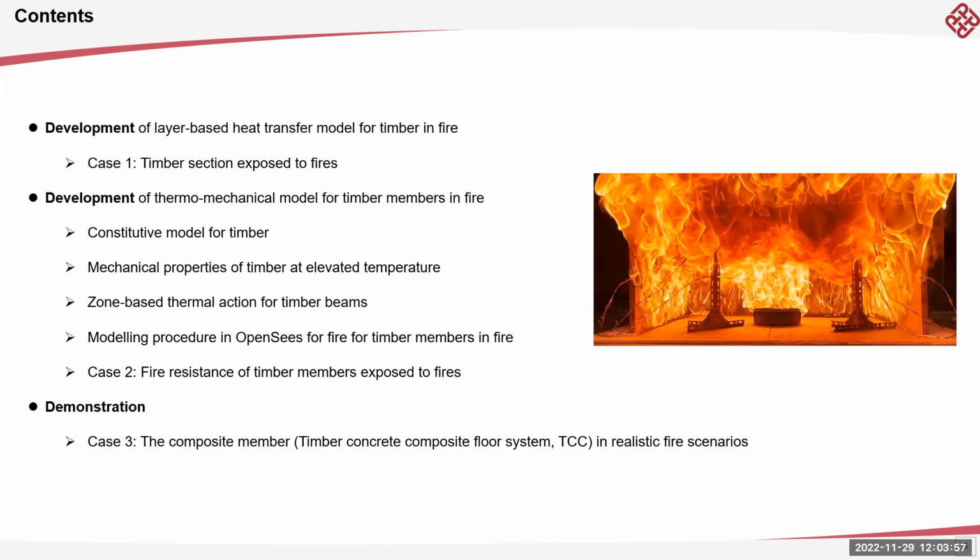And the second is development of a thermomechanical model for timber members in fire, including the constitutive model for timber, mechanical property of timber at elevated temperature, and zone-based thermal action for timber beams, modeling procedure in OpenSees for Fire for timber members in fire, and a case two about fire resistance of timber members exposed to fires. And the last one is a demonstration case about the timber-concrete composite floor system in realistic fire scenarios.